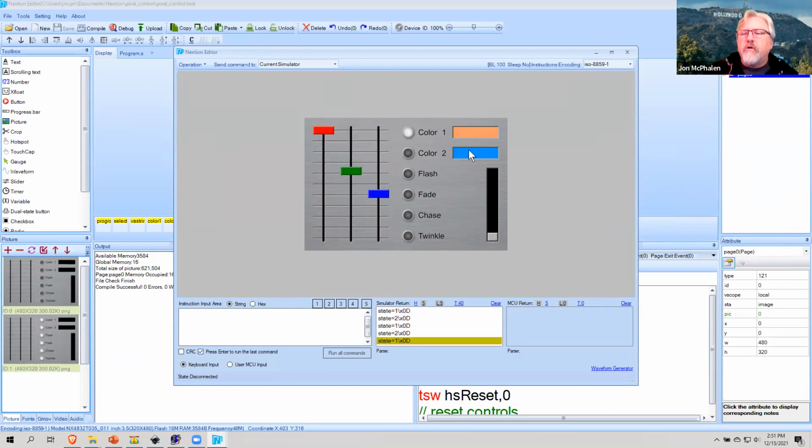So as you look through the code, you'll notice that whenever I change one of the colors, I save it as a 32-bit value that matches what the propeller wants to use for the pixels. And then I do a fill of this, because remember the NEXTION uses 565 16-bit color. So I will take the RGB values that I have and make that. So it's a pretty close approximation. I was running this today and it's pretty good.